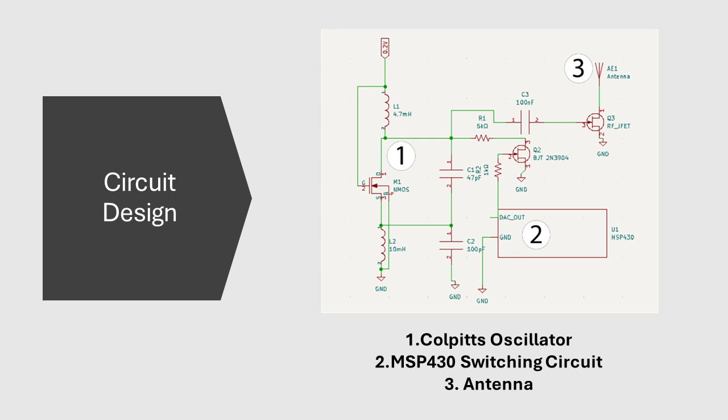The third part of the circuit, the antenna, is chosen to accept energy at a designated carrier frequency. For our application, we chose an antenna tuned to 915 megahertz, which allows energy from 915 megahertz to flow into the backscatter circuit and allows for the RF energy to be mixed up to 915 megahertz coming from the oscillator. These three components together allow for a circuit which can encode information via frequency shifts.